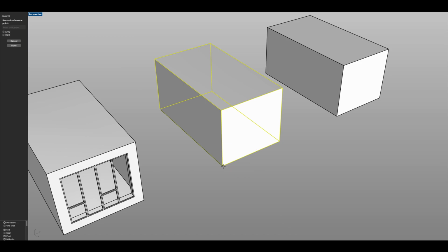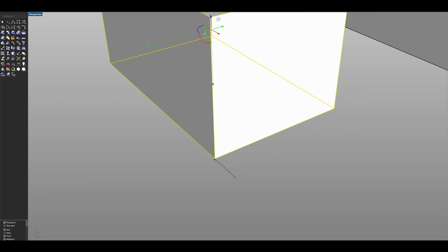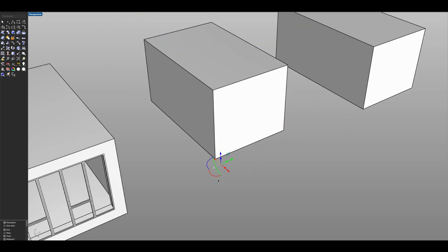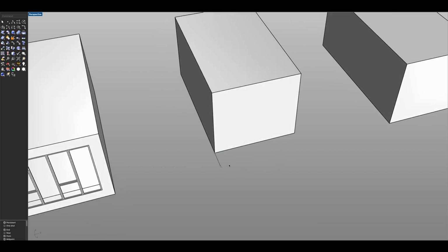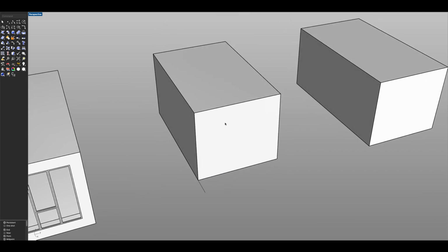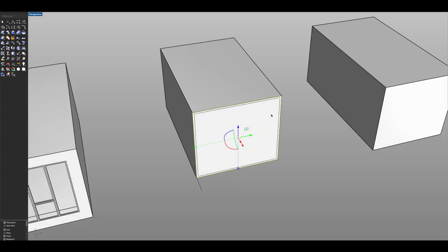Let's bring it all the way up to the front and simply back it off until we reach our balcony dimension here. And of course you can make this measurement whatever you like. I'm just going to keep this one here for simplicity's sake. Okay, the next thing we want to do is to draw a new line that covers this face here. Same process as before, and in this one I'm gonna go for offset 0.1, like that.